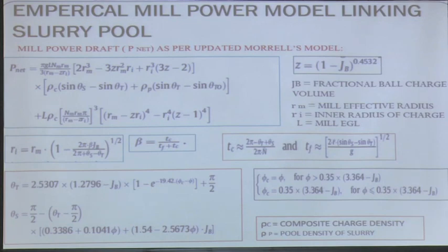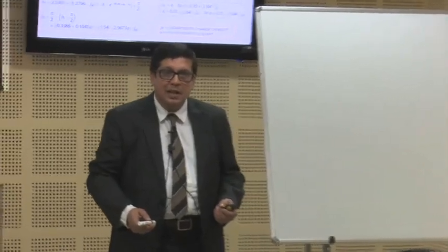Effective grinding length is totally different because two things are important, and one is the effective diameter of the mill. If we knock out the volume occupied by the liners in the mill from the mill shell, then we come to some volume. If we comprehend that in the form of a cylinder, then it will be a virtual cylinder, and the diameter of that is the effective diameter. Is this definition clear?